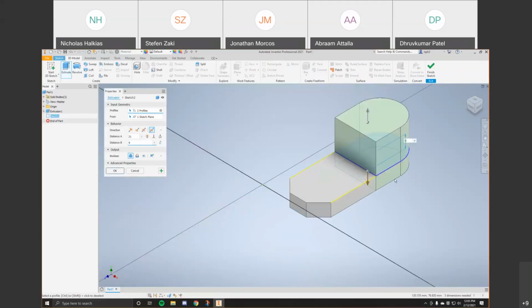So I'm just going to zoom out. Now we see that that overhang is taken care of, and it's extruding in the upwards direction 21 millimeters. Now when you have multiple pieces, you have this new option for output, the Boolean output. By default, it's to join them. You can cut it out, so if we were to select this one, it'll remove this whole back section. You can do the intersect, which will only leave this little rectangular section, or you can create a whole new solid.